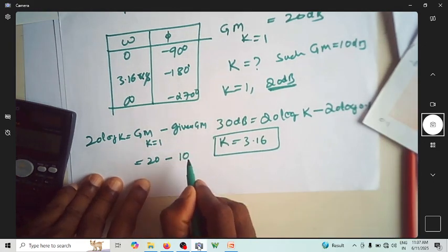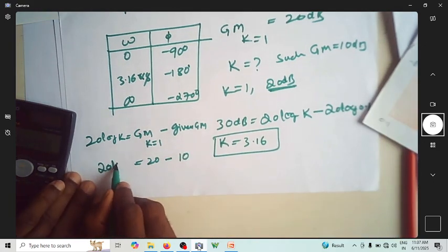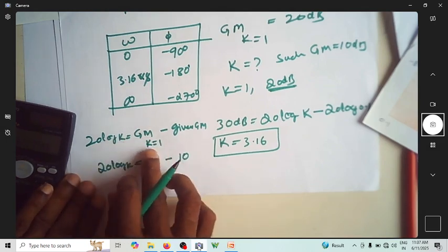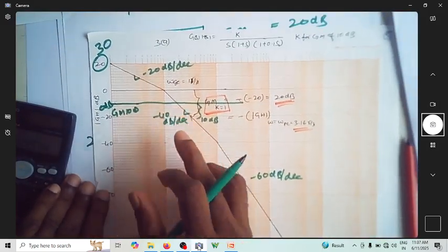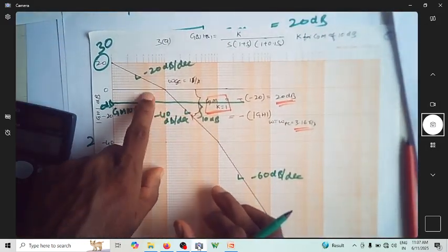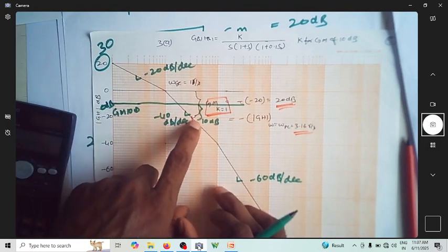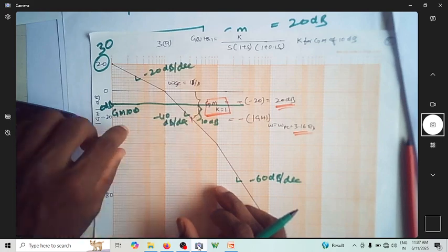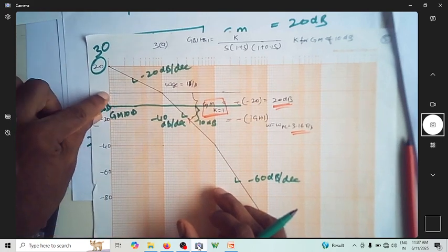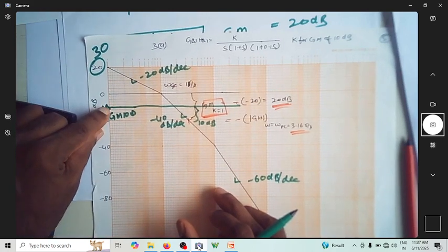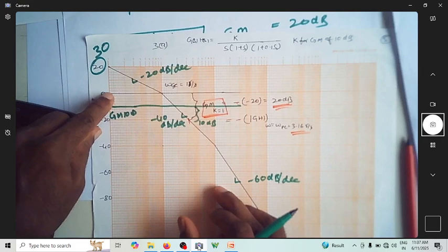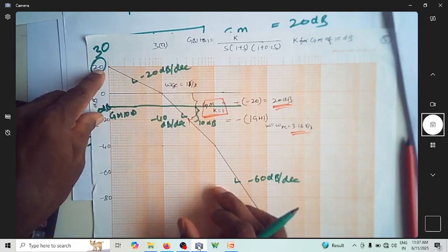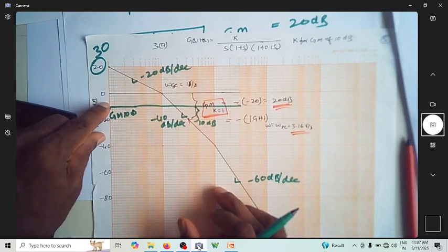They have asked for a gain margin of 10. So this is 20 log of K. This is another way of finding it, so there is no need to shift your 0 dB and all that. The previous approach is the more conceptual way of shifting the 0 dB so that the gain margin becomes 10 dB. By however much you shift up or down, by that much this will increase or decrease. If you go up by 10 dB, then this will become 10. If you come down by 10 dB...